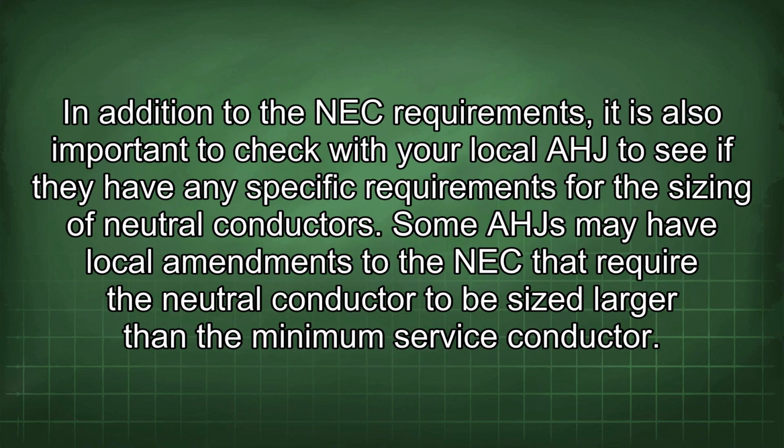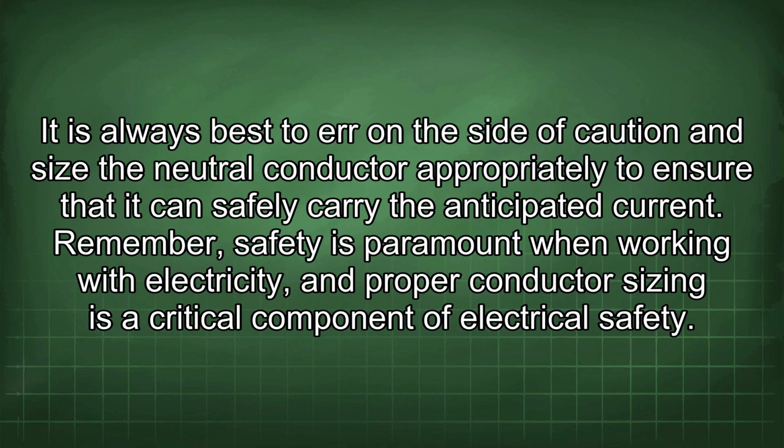In addition to the NEC requirements, it is also important to check with your local AHJ to see if they have any specific requirements for the sizing of neutral conductors. Some AHJs may have local amendments to the NEC that require the neutral conductor to be sized larger than the minimum service conductor. It is always best to err on the side of caution and size the neutral conductor appropriately to ensure that it can safely carry the anticipated current.